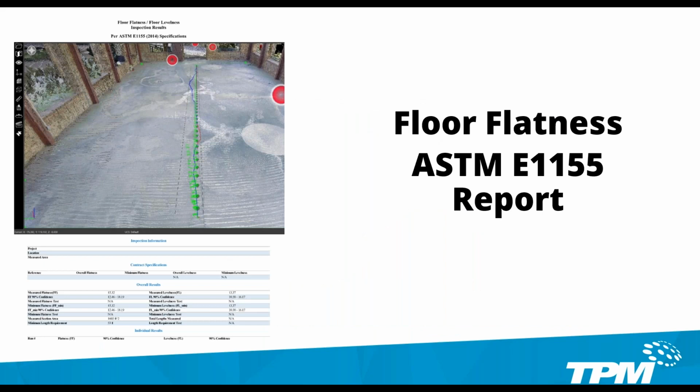And on the floor flatness line, as mentioned earlier with the heat map, there also is a formal ASTM E1155 report that we can produce with this software that will give you a direct floor flatness report based on that data. You'll see our snapshot over there, the inspection results that come across with that report. In addition to these examples, you're also able to do some deviation analysis. This is really powerful for looking at maybe a wall, seeing if it's moved, and looking at some structural analysis and integrity assessments.